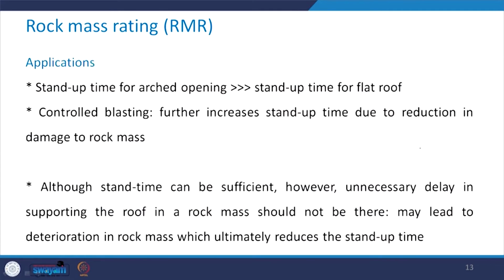Let us have some more discussion on this stand up time. The stand up time for an arched opening is much larger than the stand up time for a flat roof. So, you can have this kind of tunnel cross section or you can have this kind of tunnel cross section, where in this case you have the arched roof and in this case you have the flat roof. The stand up time is going to be larger for this case as compared to this case.